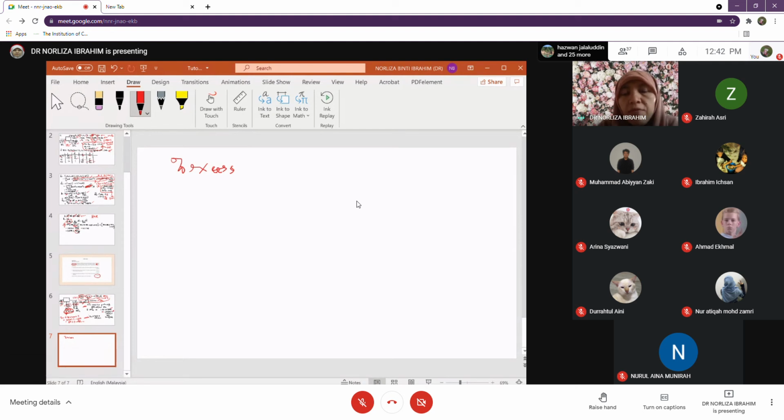So if it is mentioned 90% excess air, it is actually the same as 90% excess oxygen. So I'm focusing on the oxygen: oxygen fed minus oxygen stoichiometric, over oxygen stoichiometric, times 100%, because we use percentage. So how to find the oxygen stoichiometric?